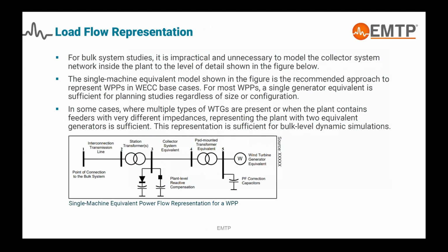In terms of load flow representation, as I will show you, we represent this system slightly differently in PSSE and in EMTP, though it could be the same, just because the client requested this format. In PSSE, we developed the six feeders, and in EMTP, we developed it as a single machine.